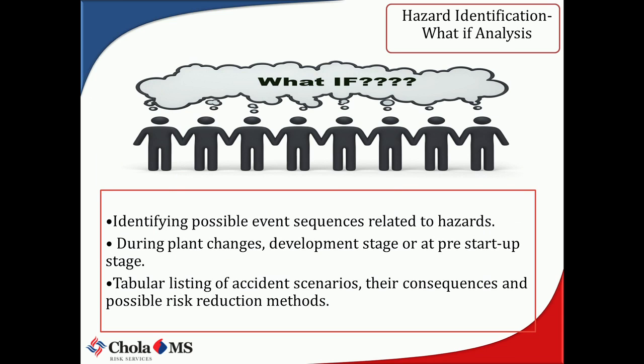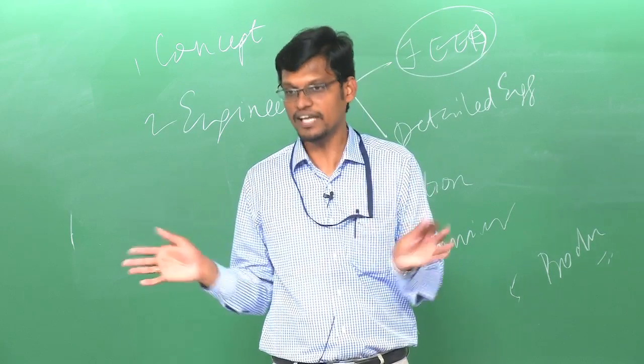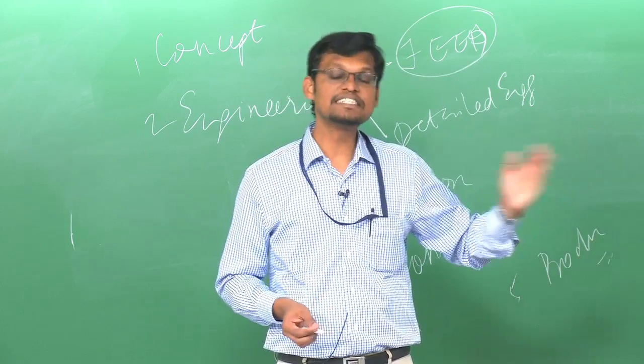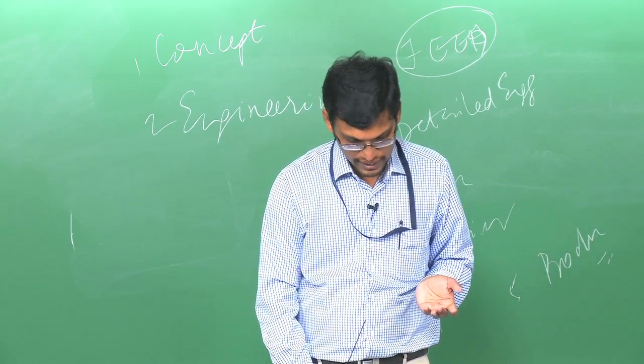Okay. This is another interesting technique. It is called what if analysis. And this you can use in process, you can use it in manufacturing, or in any other process where you want to use it. The beauty of this technique is that it helps you to brainstorm. Again, it is a team exercise, it is not like one guy sitting and writing the whole thing. So, the what if questions will lead you to analyze more.